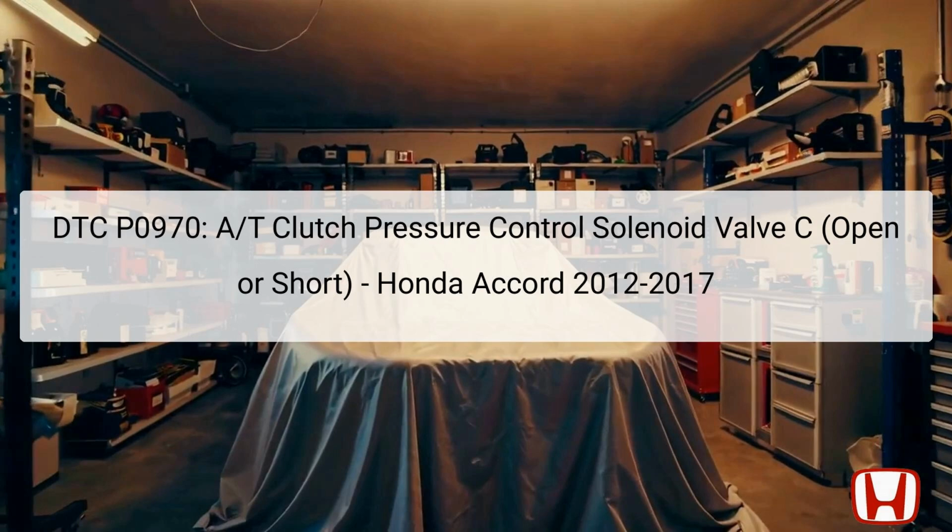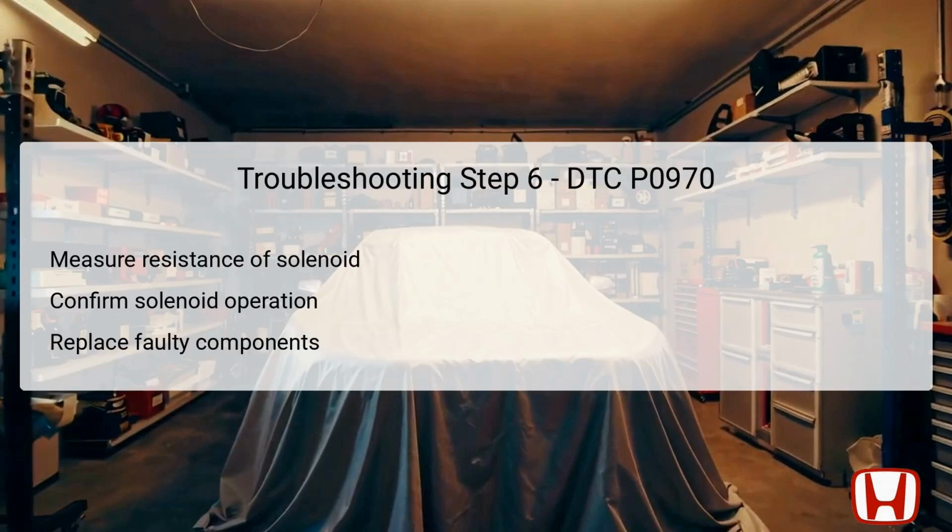Data such as freeze frame and onboard snapshots should be recorded prior to starting the troubleshooting process to ensure a comprehensive overview of the issue. The final troubleshooting step involves checking the AT clutch pressure control solenoid valve C directly by measuring the resistance between the designated test points. Ensure that the solenoid connector is disconnected and that the PCM connector remains unplugged during this measurement to ensure accuracy. The specified resistance range for the solenoid should be between 4.7 to 5.9 ohms.